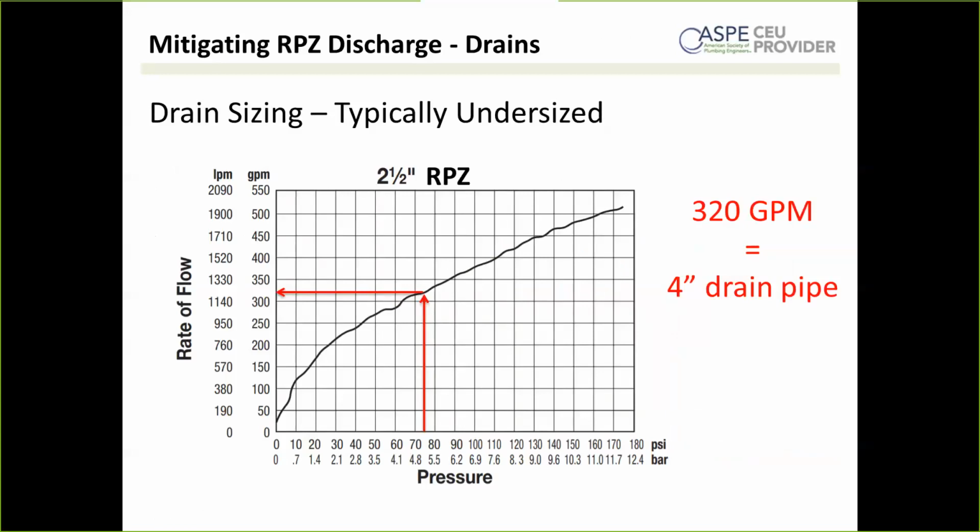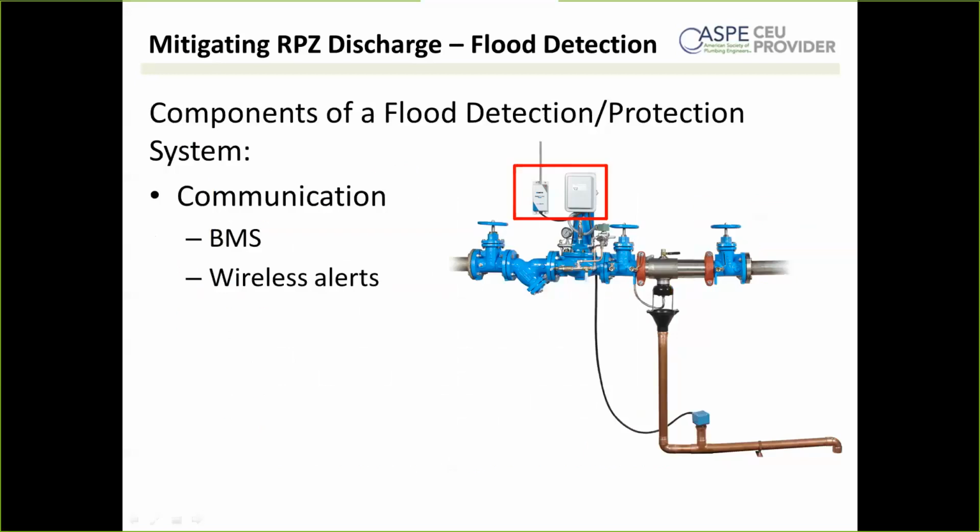How much time between the catastrophic discharge and shutdown of the incoming water by the sensor and equipment? So that's a great question. This is something that you can actually control. So in the case of this valve, right, so we have exactly how you're sensing, right? So here's your wet switch, kind of where those probes lay in the pipe. You have the timing, so how long do those probes need to be activated? So this works with all the different manufacturers. How long do we have to sense that relief valve is open, that there's water in the drain pipe before you activate? Because different people, different applications are going to be more or less sensitive.